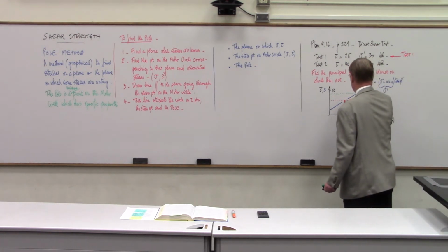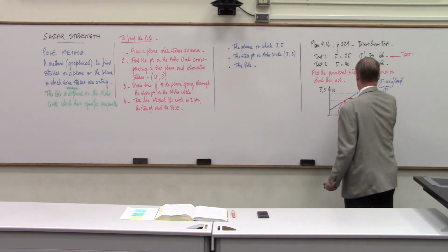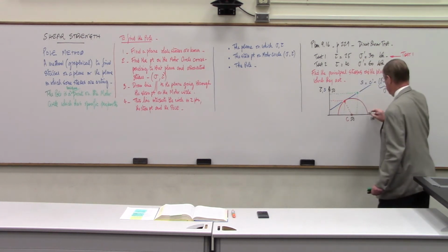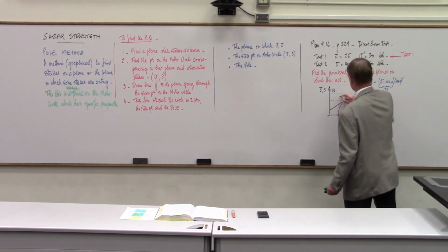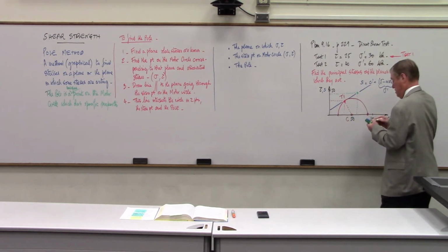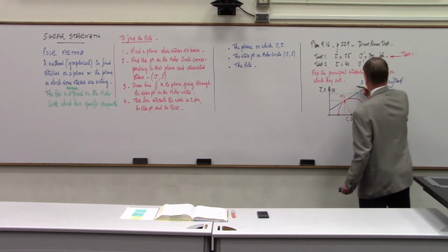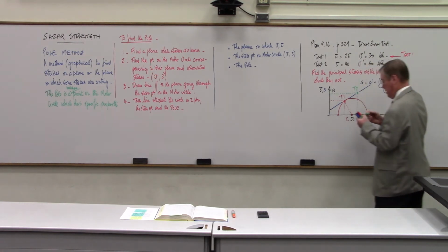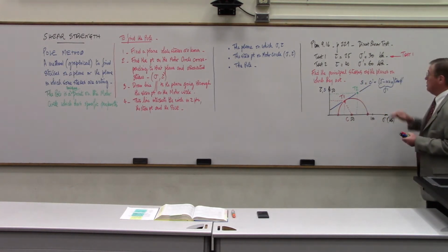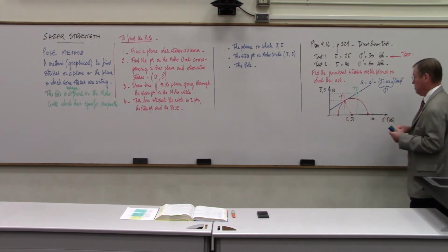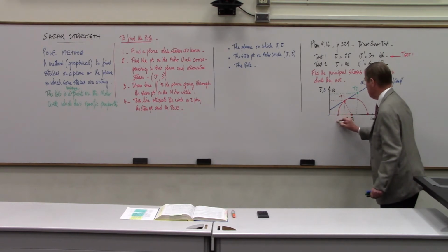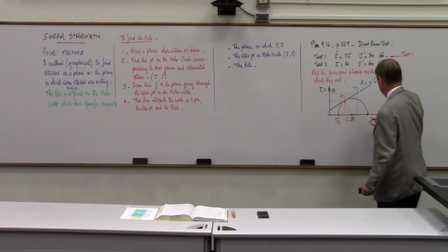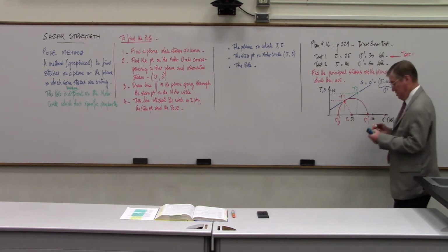And then we complete the Mohr circle, and that gives us the Mohr circle for that test 1 here, test 1. And this would be test 2. Now we're going to do the same thing for test 2, but we'll stick to test 1. So then, what are the principal stresses? Well, you know the principal stresses are the stresses that are on planes where the shear stress is 0. So this is going to be sigma prime 3, and this is going to be sigma prime 1.